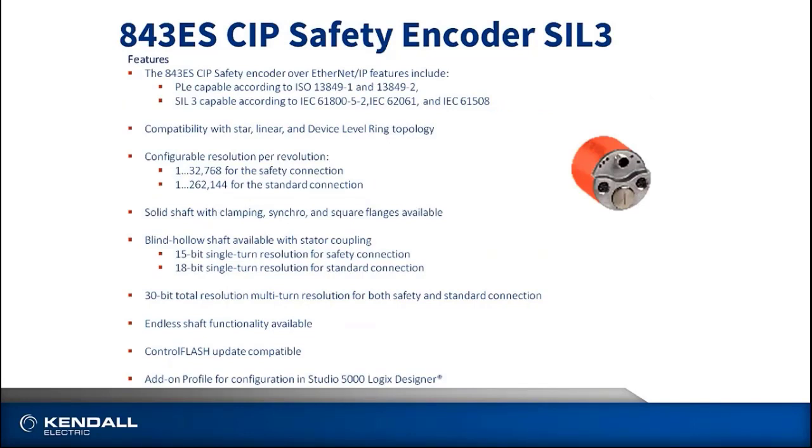A list of them is up above on the top here, of all the different safety functionality it hits. We can do star, linear, device level ring, resolutions of up to 15-bit for our safety functionality and 18-bit for our standard operations, and it's available in many configurations from solid shaft, hollow shaft, just like most encoders we'd expect today.